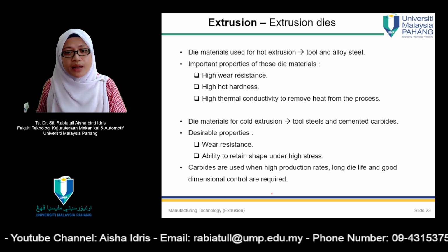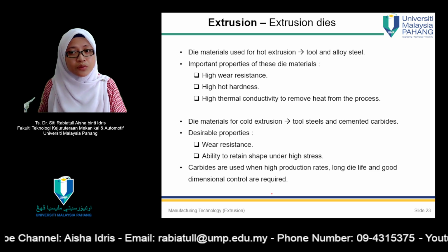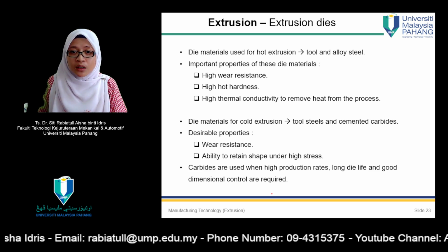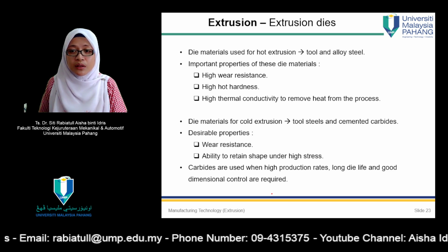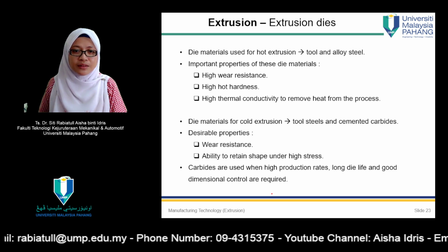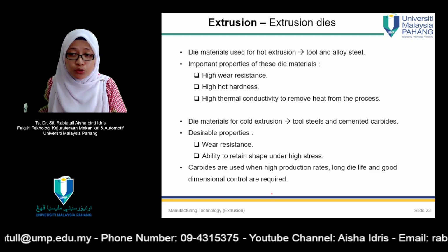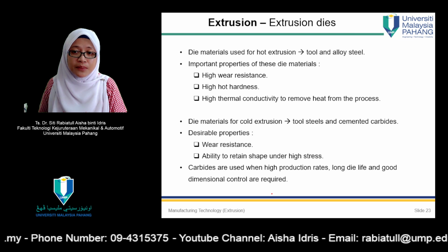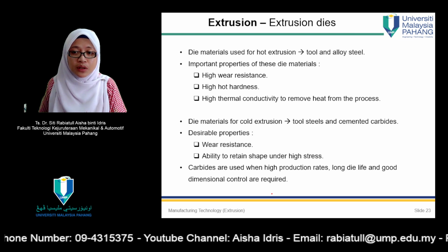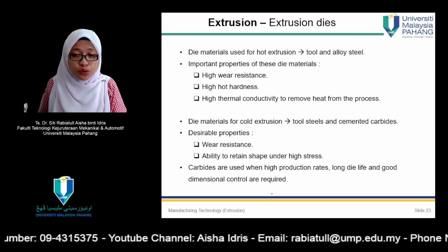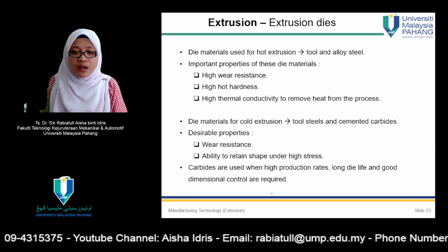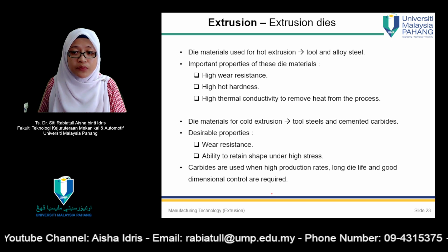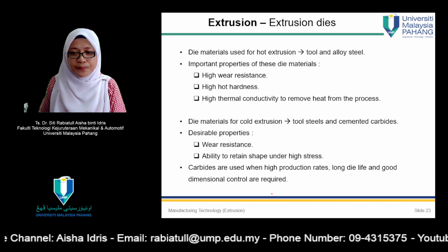In extrusion there are also extrusion dies that we need to look at. The die material used for extrusion is normally tool and alloy steel. The important properties of these die materials include high wear resistance, high hot hardness, and high thermal conductivity to remove heat from the process.